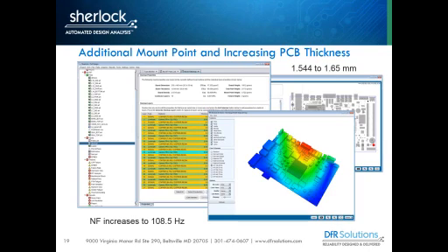Again, this has got an edge card connector. I have to make sure that my printed circuit board, within tolerance, can still fit within my edge connector. So there's a lot, you can't just change these. You have to check with the electrical engineers and the mechanical engineers to make sure what I can do to the circuit board as far as thickness.